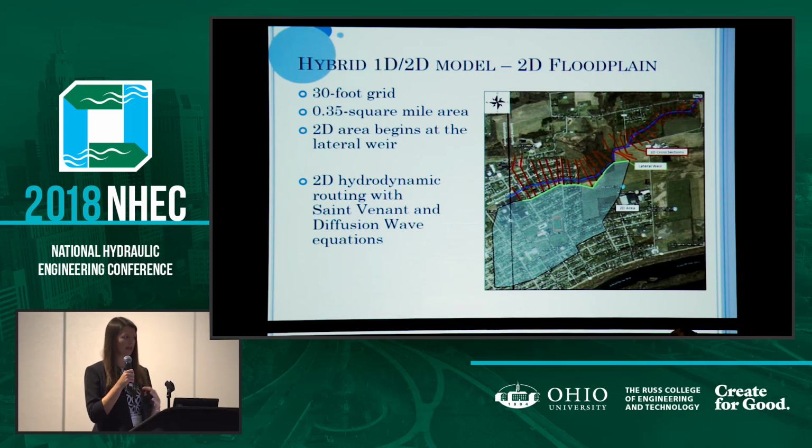So using those calibration tools and sensitivity, we determined that nearly half of the 100-year flow leaves the system and spreads into this southern floodplain area. This resulted in a 100-year flow of 270 CFS at the downstream-most limit of our model.